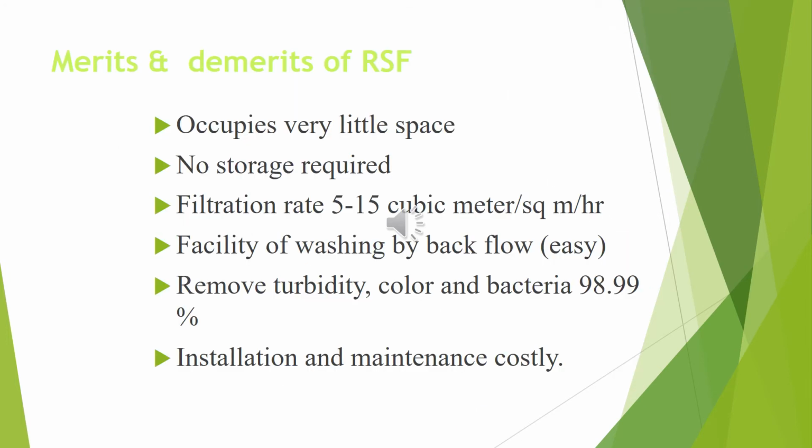Now coming to the advantages of rapid sand filter, it occupies a very small space as compared to the slow sand filter, but it is very costly, and usually it needs operation by trained staff, and there should be a facility of backwashing by backflow, which is easy, but it needs to be done frequently as it gets very dirty. Now there is removal of turbidity, color and bacteria of 98 to 99%, but its installation and maintenance is very costly as compared to slow sand filter.